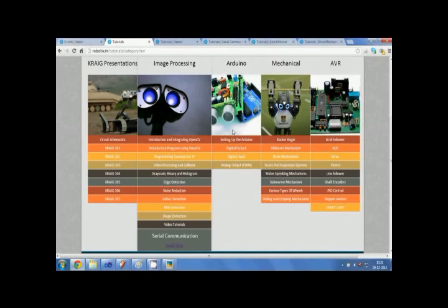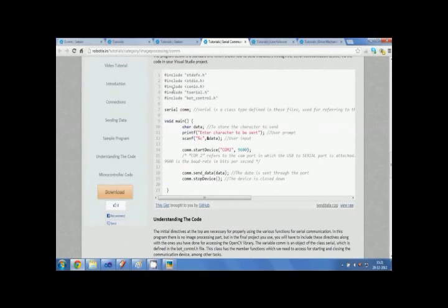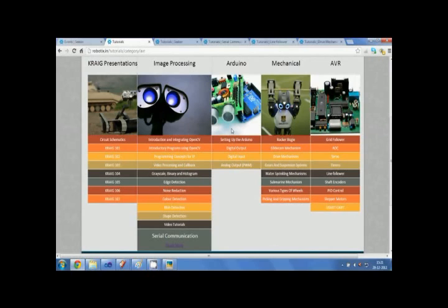Now, how will we connect this to our image processing? You're going to write your image processing code either in Visual Studio or some other IDE, and the program that runs from here is going to send a certain character through serial communication, again for which we have included sample code here. When the microcontroller receives that character, its code has been burnt in such a manner that based on certain characters it receives, it instructs the motor driver to make the motors move in a particular direction. A very popular combination, and the one most widely used, is WASD.